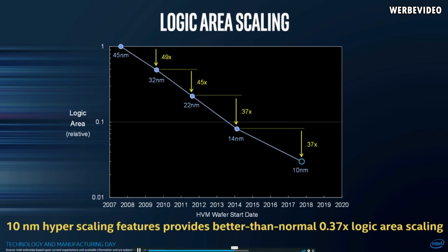However, this figure reflects process history. Just looking at, for example, 90 nanometer, 65, 45, 32 nanometers, all of those have the factor 0.7 within the name, just going from like 90 to 65. The reason for that is we're looking at a structure on a surface. And if you have a factor of 0.7 in length on the surface, like 0.7 times 0.7 equals about 0.5, which means that we have double the amount of transistors.